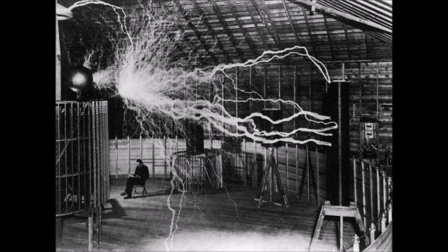Thank you. Hello everybody. Let us look at how does wireless power work. The basic of wireless power involves the transmission of energy from a transmitter to a receiver via an oscillating magnetic field. To achieve this, direct current supplied by a power source is converted into high-frequency alternating current by specially designed electronics built into the transmitter.